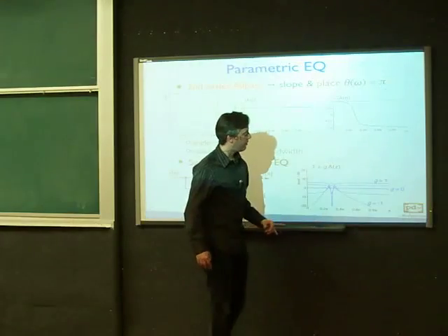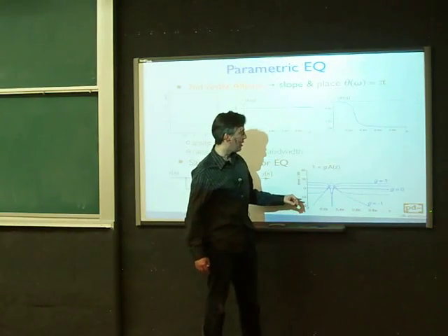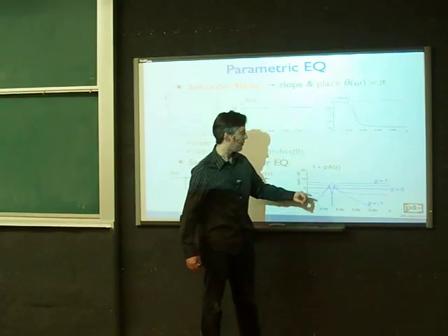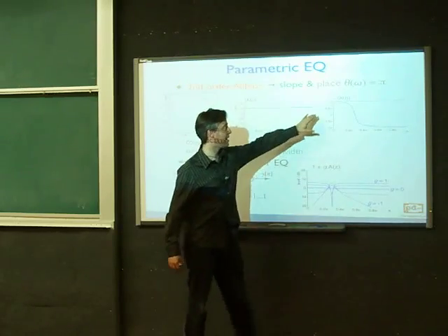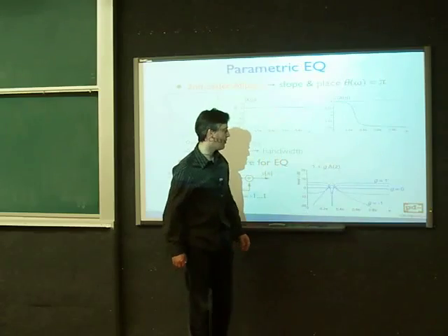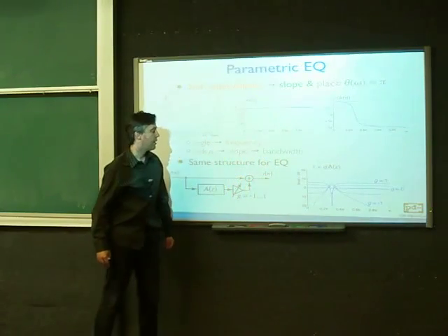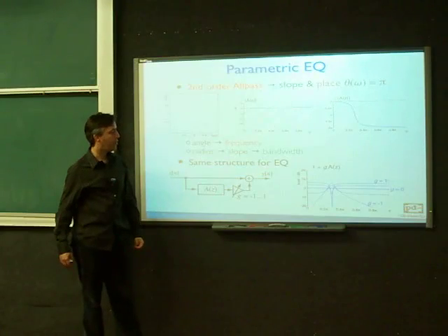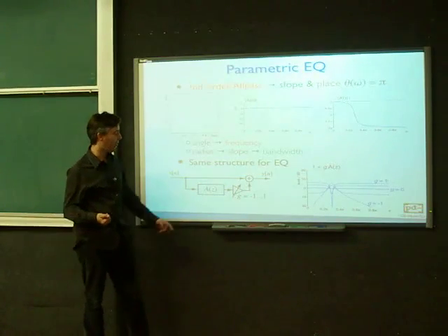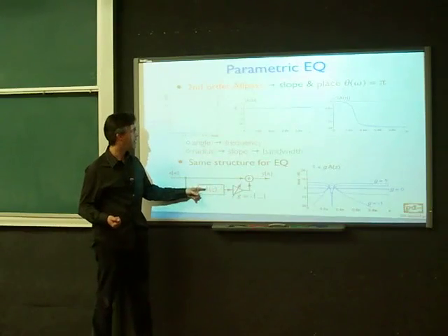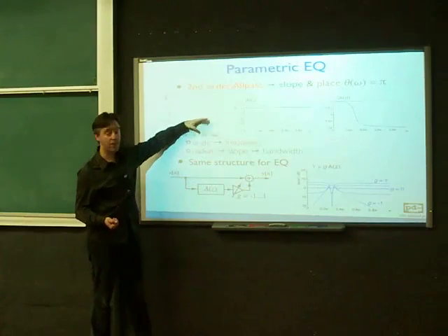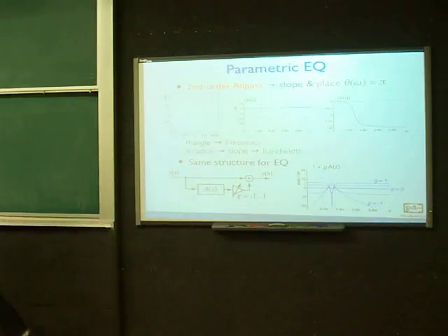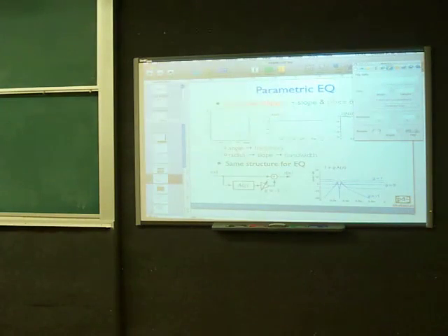But now the set of frequency responses we get is like this. When we add it, we get a notch filter. And when we subtract it, we get a bandpass filter like this, because we're cancelling out the two extremes. Before we had one parameter, apart from the gain, which was the radius of the pole. Now we've got 2 parameters we can change, the radius and the position of the pole 0. So let's have a listen to that in PD.